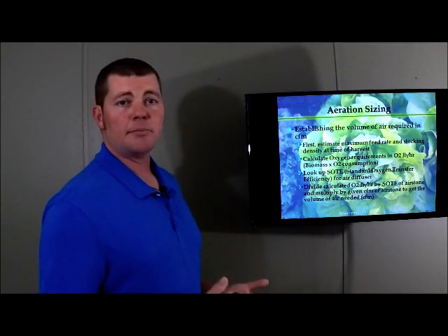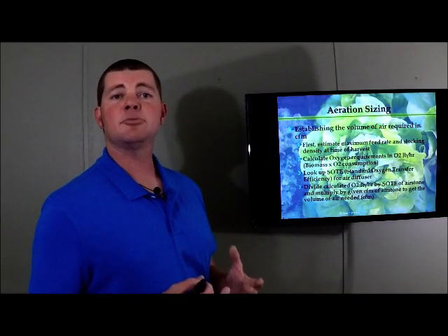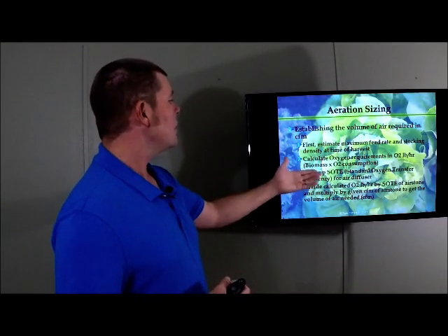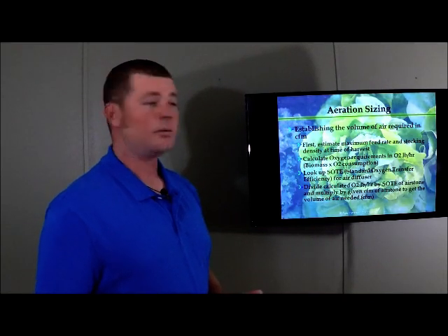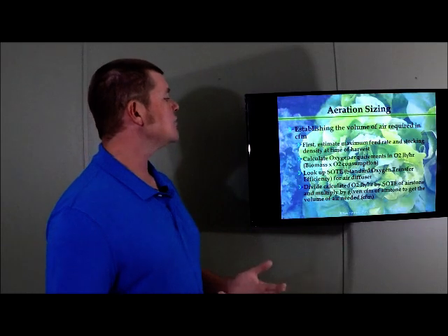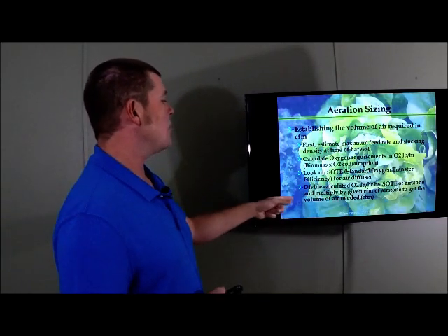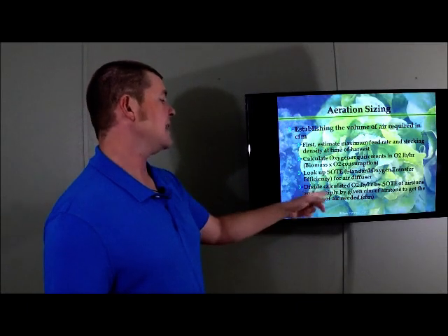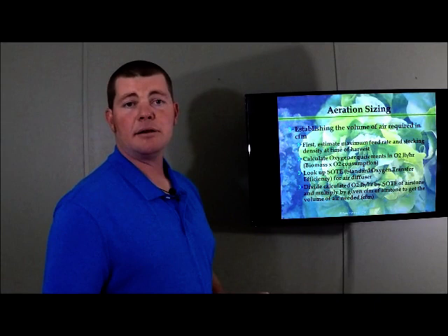That's very important because not all diffusers are the same. If you have a very large bubble, you'll get a lower standard oxygen transfer efficiency than if you have a smaller bubble. Now we want to divide that calculated oxygen pounds per hour by the SOTE of the air stone and multiply it by the given CFM of the air stone to get the volume of the air needed.